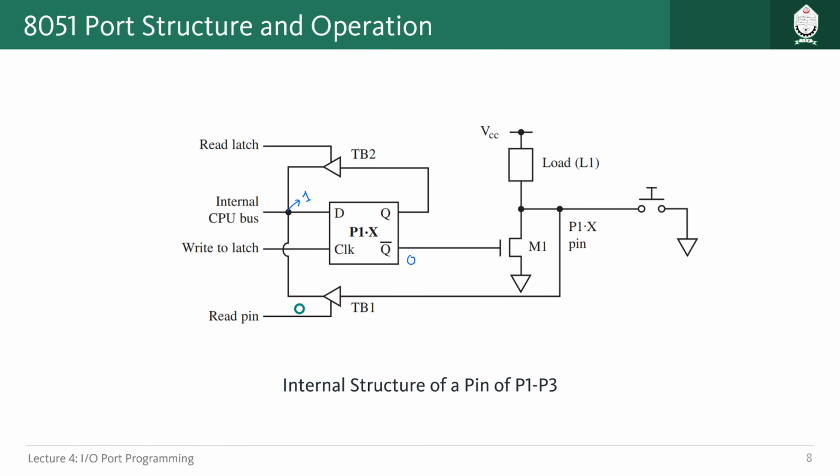But still you see this thing is here and current can flow from this path to this path. So we are unable to completely shut down the flow of signal from inside of the microcontroller to outside. So it is not truly bidirectional. Whenever we mean truly bidirectional, whenever one of the directions is giving a signal, signals from the other direction will be completely shut off. That is not possible for this particular circuit.